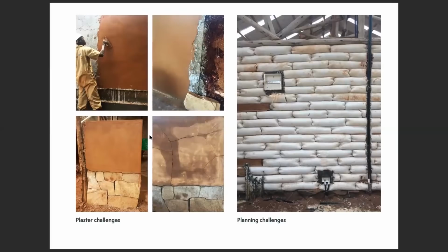But what you must understand is that working with lime is very difficult for many reasons. First, it breaks easily, it cracks easily, and this can of course be avoided by incorporating things that will deal with the tensile strength, like we are using mesh. Some people use fiber in the lime. The same with earth. We also have to incorporate fiber to make sure that it holds together, because of course when it dries, it will tend to shrink and break apart.